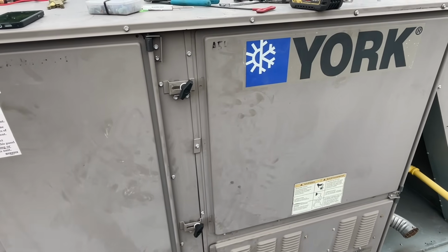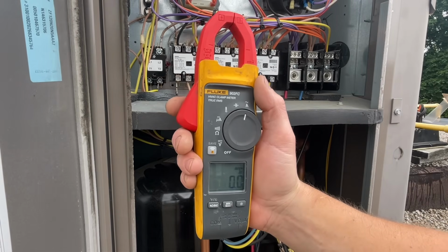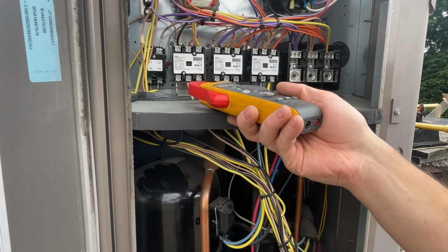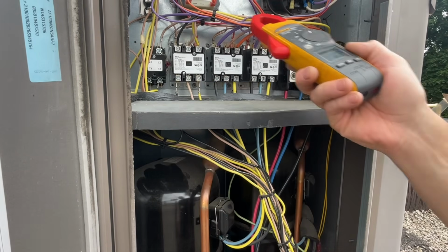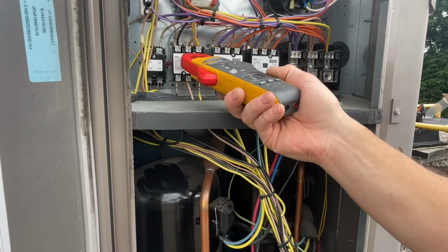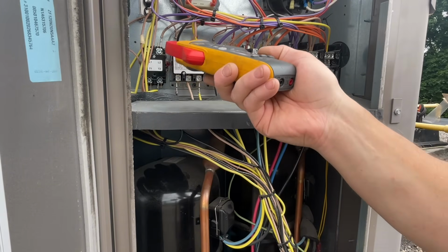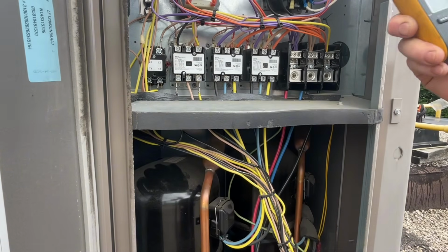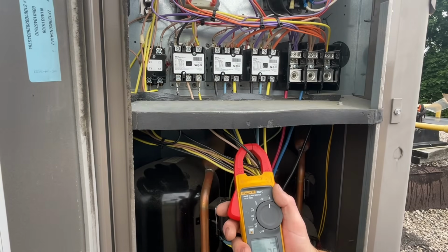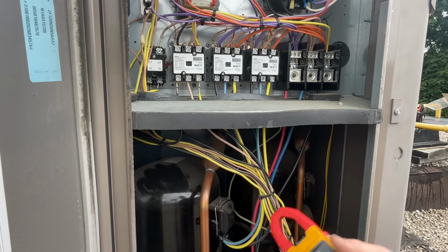Perfect. We're gonna check our amperage on our motor now. We're gonna use this clamp meter. I find this the easiest way to check amperage. We're gonna check our load side of our contactor. So not our line voltage in from this terminal block, but the outlet side. When this is energized through a call for the fan on the thermostat, contactor pulls in, allows voltage through each leg driving our motor. So we're gonna check all leads. So we'll check our black lead first, which we have, let me try and show you guys, 3.6, 3.5.